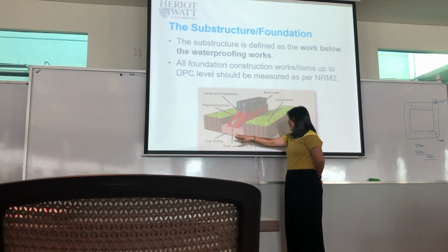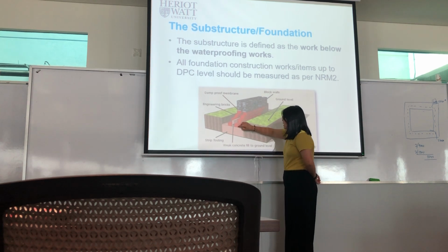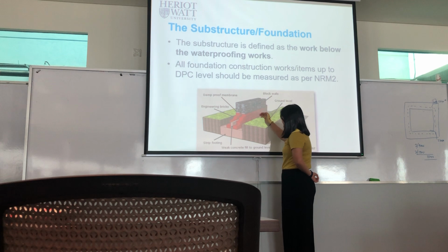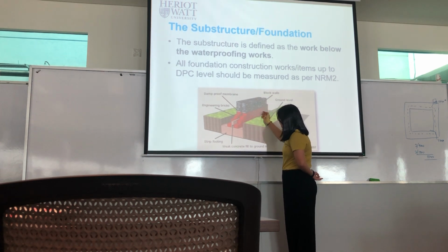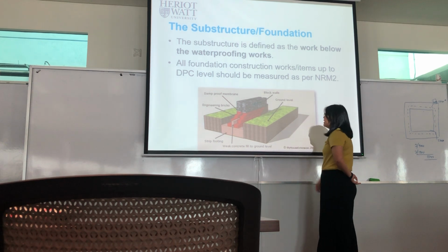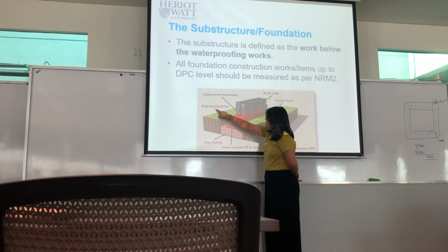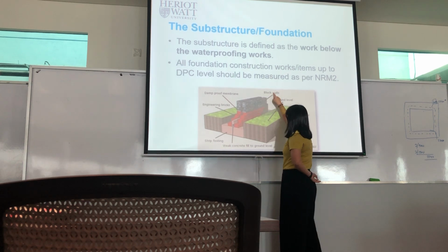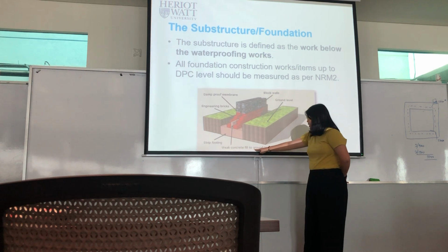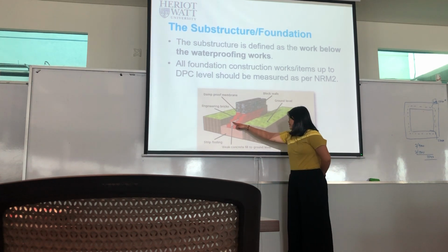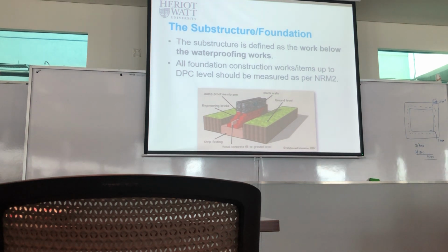Right? So, in this case, we are going to do a strip footing only. Then you erect the walls, all the necessary, and you will have to fill it. So this is the damp-proof membrane. Okay, this is the engineering bit. This is the blockwork, and this is the ground floor, strip footing, with concrete filled to ground. So this is just a concrete just to fill it. Okay. So this is just an introduction.